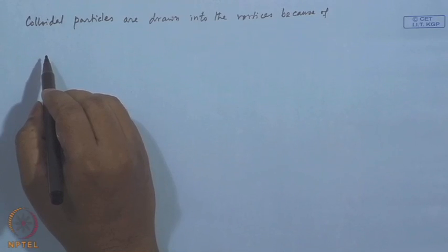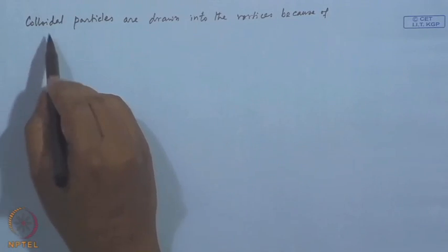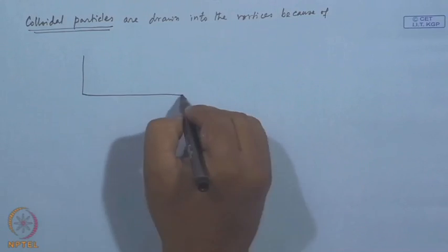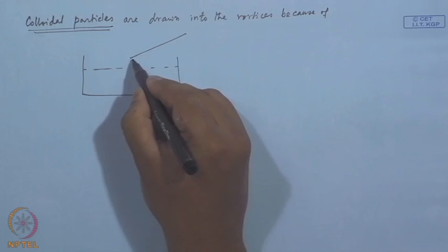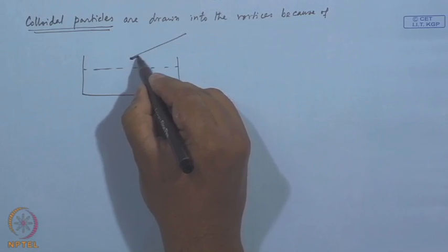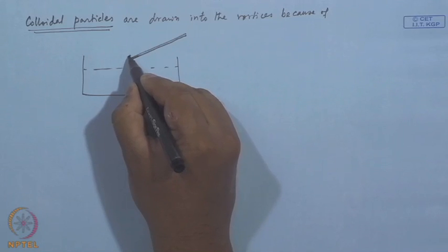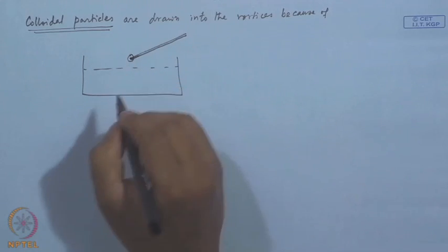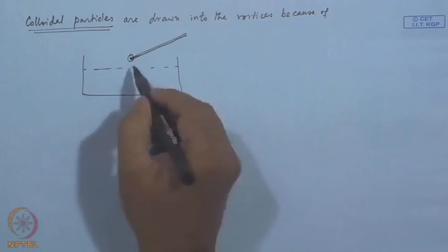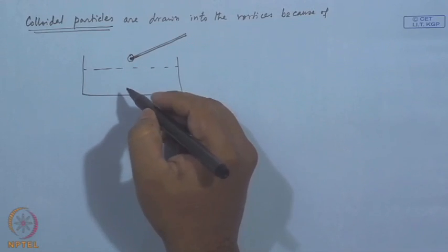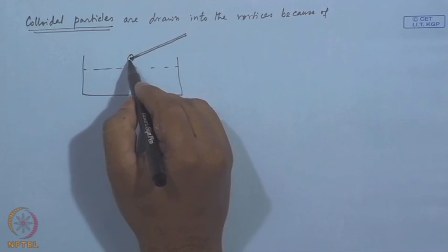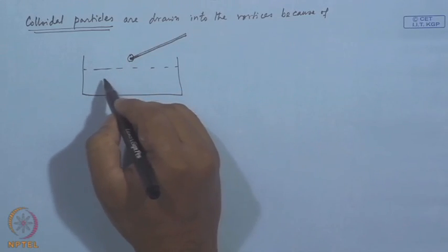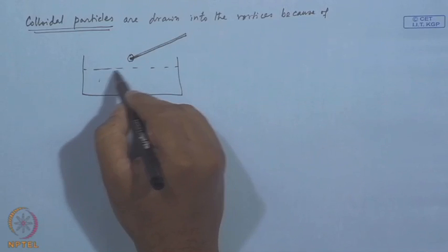So, these colloidal particles will be, see this is another mechanism. What we are talking about here is that this is the liquid pool inside the cavity, and the electrode is brought in here, a tip electrode, that is called corona electrode, a very sharp tip at a very high voltage. So, that is brought in here, and this distance is small. So, near the interface, the colloidal particles will be pulled by DEP force, closest to the corona electrode tip.